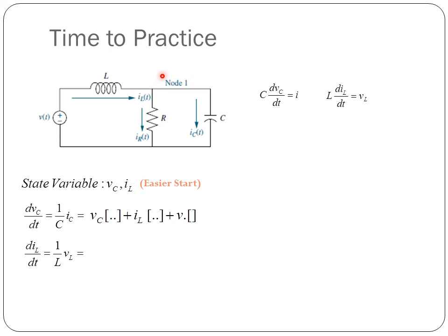So we can write all these equations from the circuit using KVL or KCL or Ohm's law, like VR is equal to IR, where VR and VC are there. Because these two are parallel, they should be equal. So we can use all these equations to replace IC using these 2 variables. Can you do that? Similarly, we can replace VL with this VC and IL, and also with V. I hope you can do it yourself.